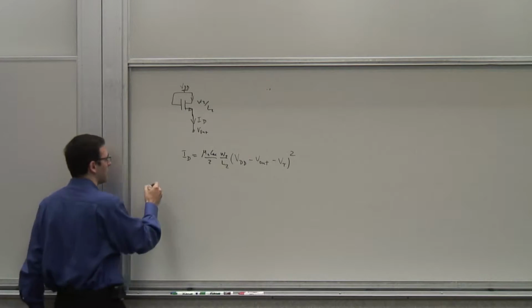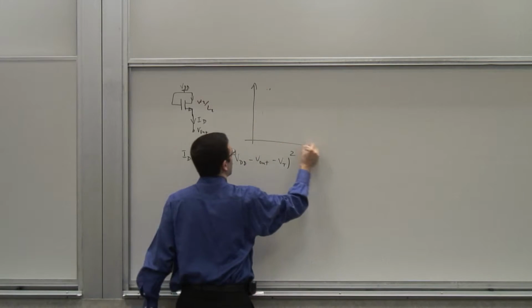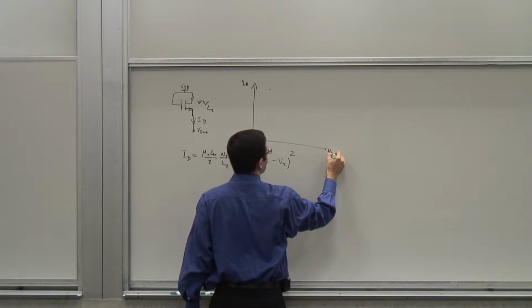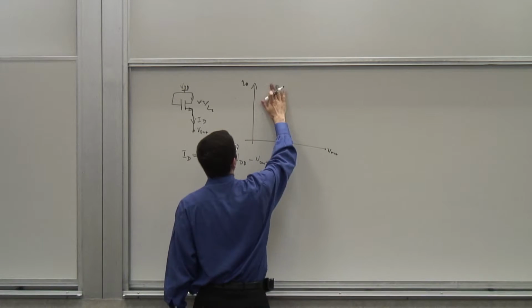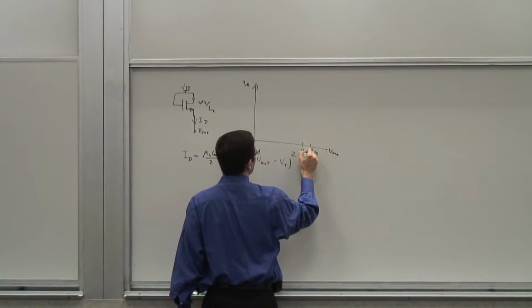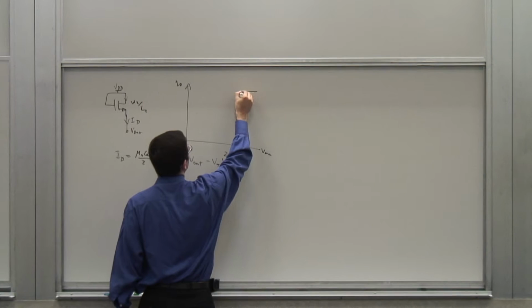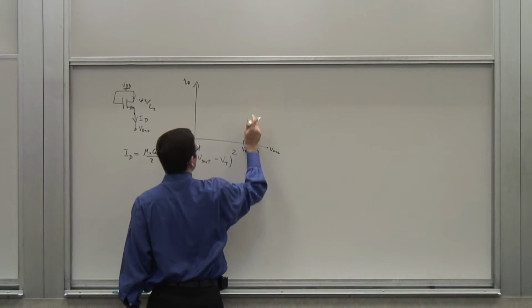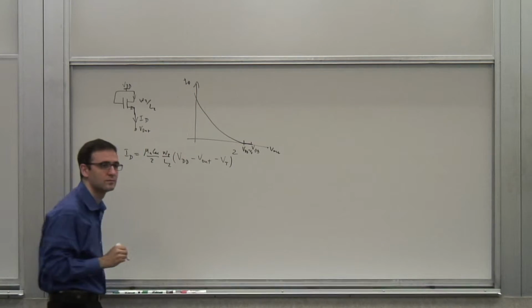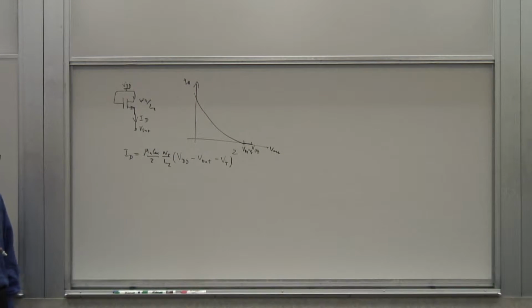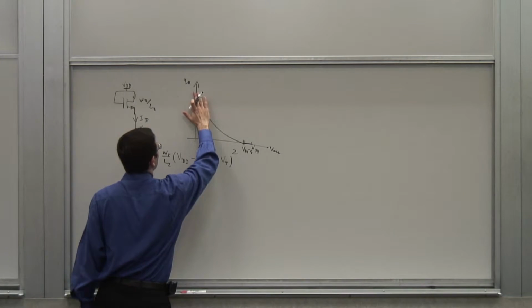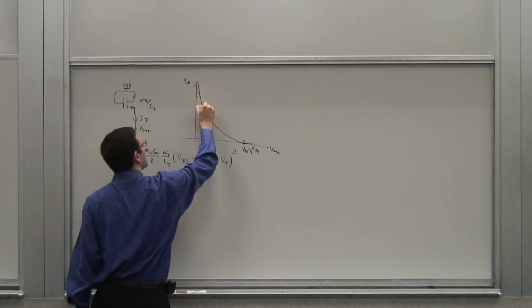And if I were to plot that, it would look like this. So it is ID versus V out. It's going to be up to certain points. So this is VDD. This is VDD minus VT. Up until here, the transistor is off, so the current is 0. And then it goes quadratic. Right? So it's a quadratic dependence. Quadratic looking.